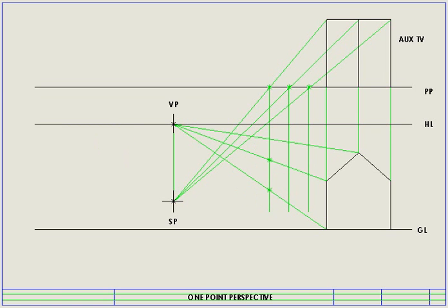Okay, now that I've found that there, I know that I need to find the apex of my roof on the other end. So I'm going to follow this projection line, which connects to the picture plane, and look at where this line goes. It actually intersects with the apex. I'm going to just undo that for a moment and redo that. There it goes. Follow it there, down below, there. Okay, so this apex of the roof will connect to the apex at the back. These 2 points have been found, which is representing that 1 point.